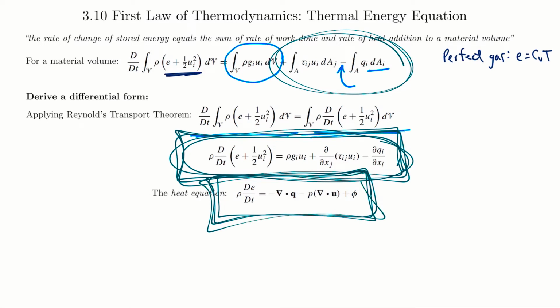That's the heat equation, very important. And what that says is E is our internal energy. So on the left-hand side, the internal energy increases because of what's on the right-hand side, which is the convergence of heat, volume compression, and heating due to viscous dissipation. These terms we saw previously in our mechanical energy equation, because that's the conversion of kinetic energy into internal energy. So that's why in the heat equation those have to be added, so the signs are flipped, because now they're contributing to the internal energy equation. So again, the internal energy increases because of the convergence of heat, volume compression, and heating due to viscous dissipation.